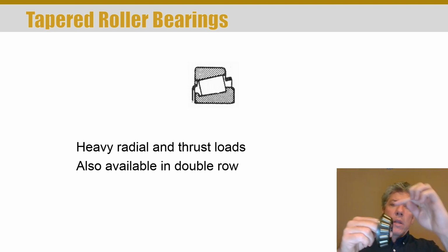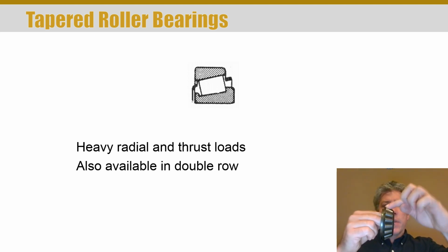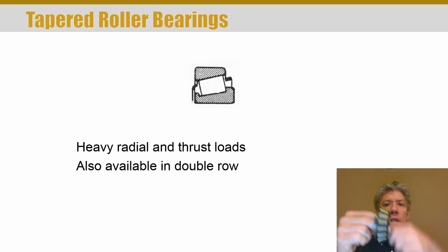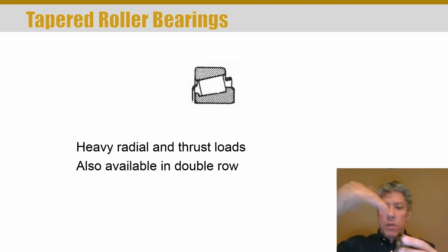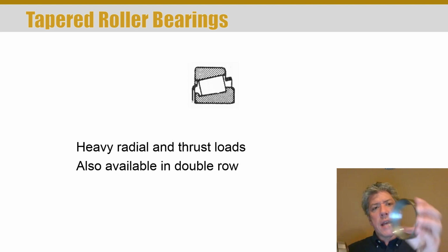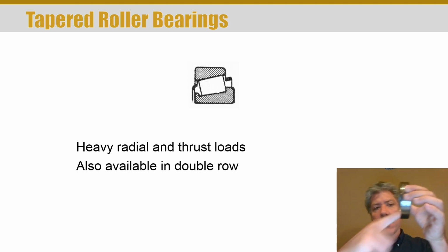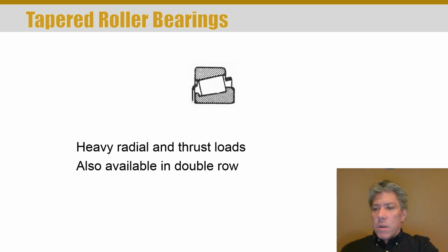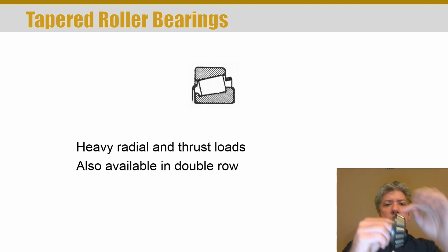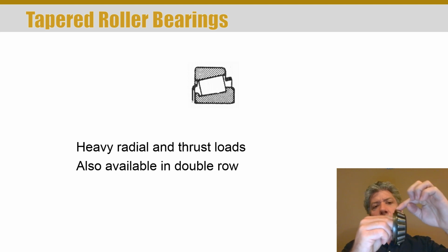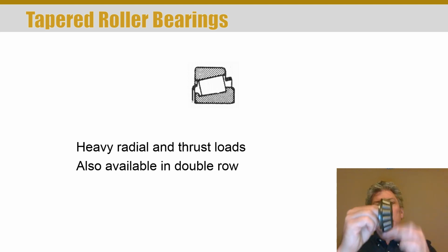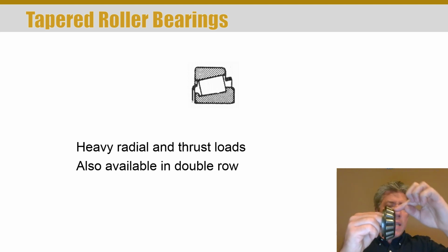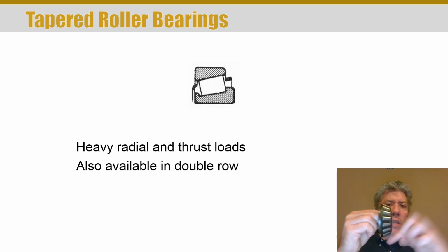the upper edge has to rotate around a longer distance, because this inner bearing is also tapered, and maybe you can see it on video. The outer raceway is also tapered. There's a taper like this on it. And so the distance that the outside diameter of the rolling element has to travel is farther than the distance the inside diameter of the rolling element has to travel.